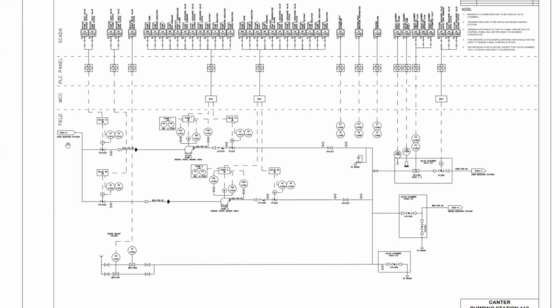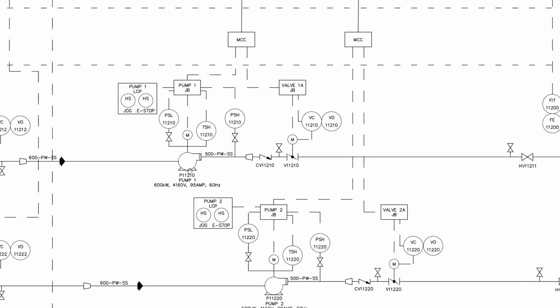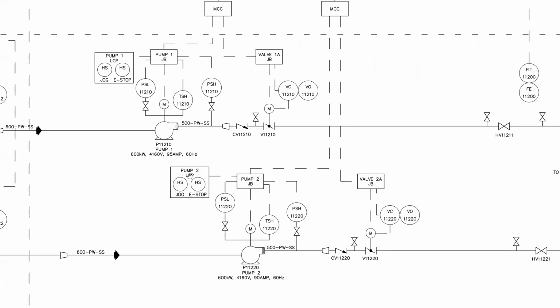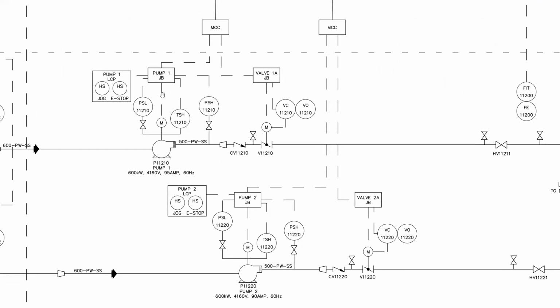So you can see here some of the things that I'd look at very quickly. We have, again, 2 pumps, and then you can trace up here, pump 1, pump 2. You see these lines that leave the pump, they come up. This indicates here we've got pump 1 wired back into pump 1 junction box.